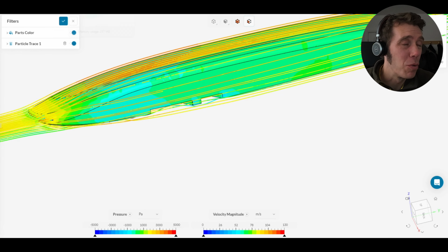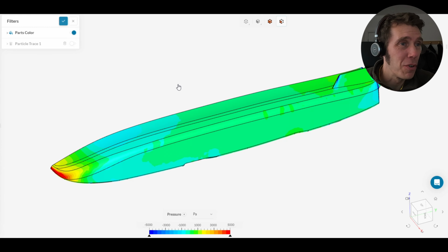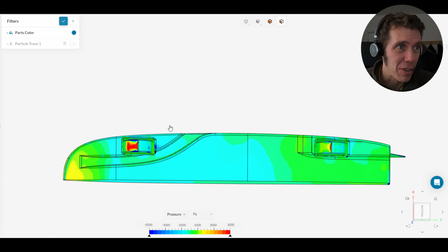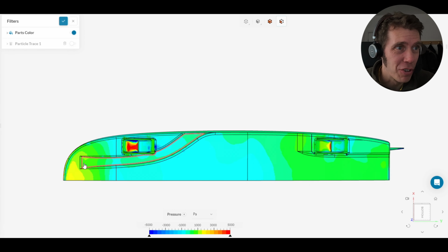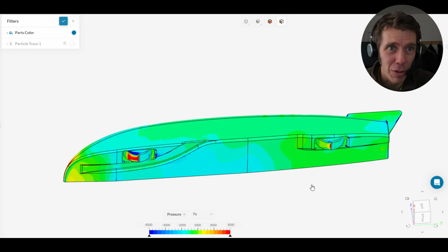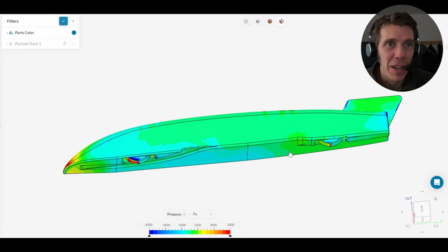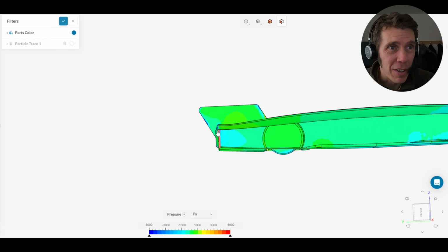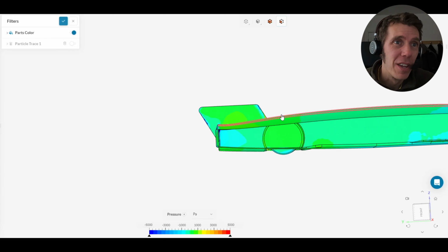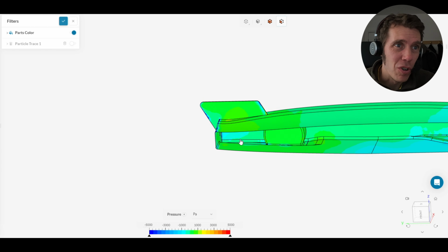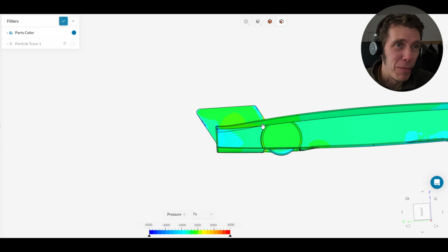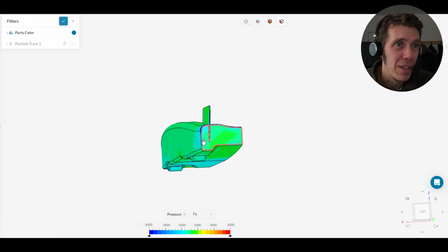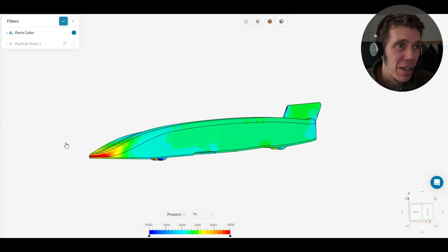Before that, I'm just going to show this other option that I considered. So this is the one that was more inspired by the JCB Diesel Max. It's just got the vent that goes from the front out to the side, and it's got a little shield bit that goes in front of the rear wheel. Another big change I made on this model was that I thickened the rear edge of the shell and had a little flick up there to try and get some rear downforce, probably at the sacrifice of some of the low drag coefficient. So it'll be interesting to see how that performs.